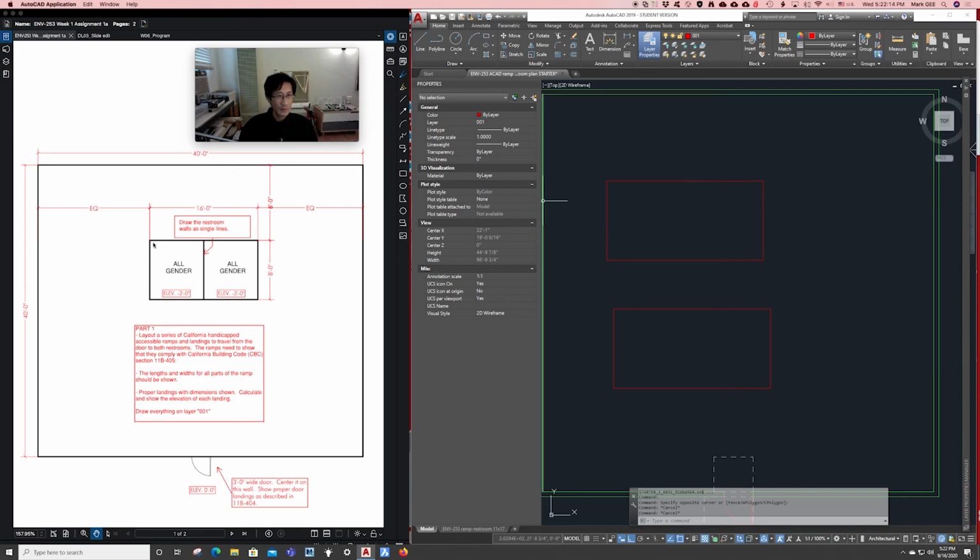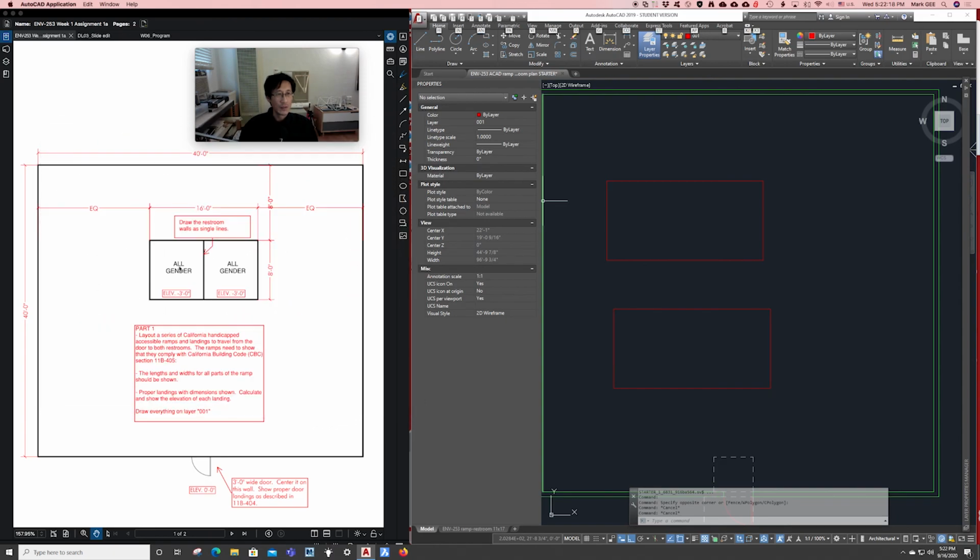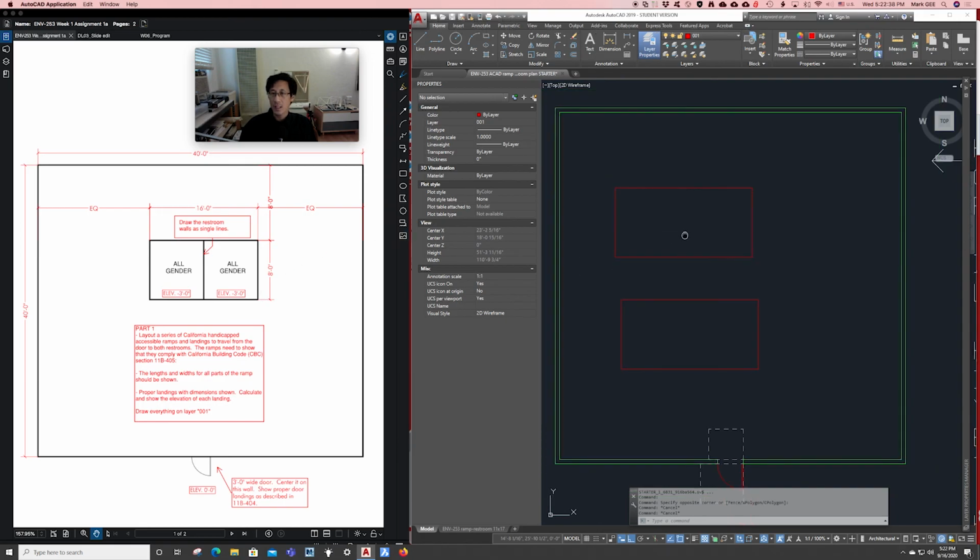So for example, if we wanted to draw the outside rectangle here, we'd start with the top left corner and tell AutoCAD where the opposite corner is down here. Where is that relative to the first one in relative coordinates? It's positive 16 feet in the X direction and minus 8 feet in the Y direction. All right, so let's practice that here in AutoCAD.